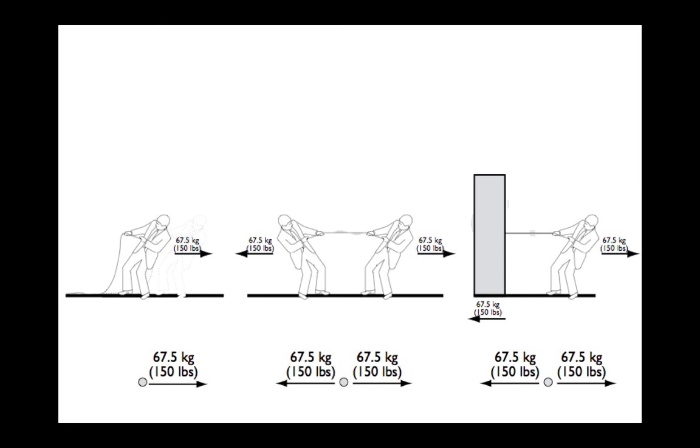So in this case, all of these arrows are actually going in the same direction, but some of them are positive, which we can say is maybe going to the right of the slide, and some of them are negative, going to the left of the slide. These are important because we can use the size of the arrow and the angle and the sense to actually do what's called vector algebra, to add these arrows up. We can do that mathematically, looking at how far in the x and y directions the arrows go and adding those up. Or we can even do it graphically. We can draw these in AutoCAD as what are called force polygons, and we can use the geometry of the arrows. We can simply maneuver them around to find out how they add up.